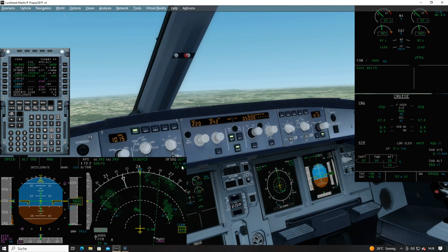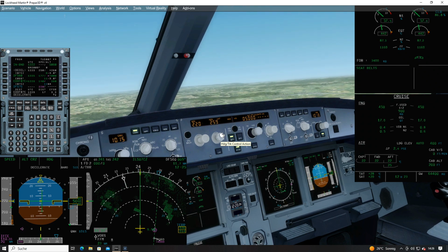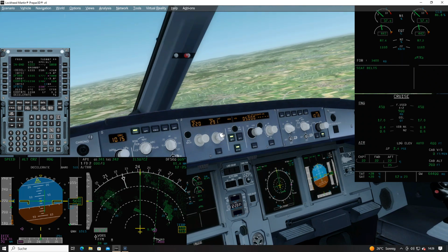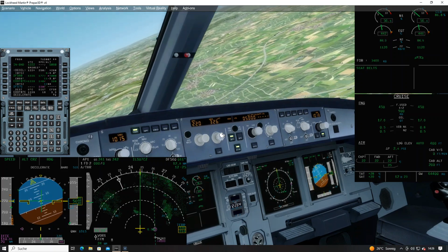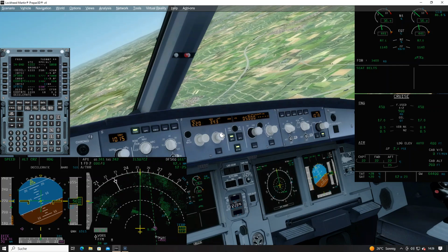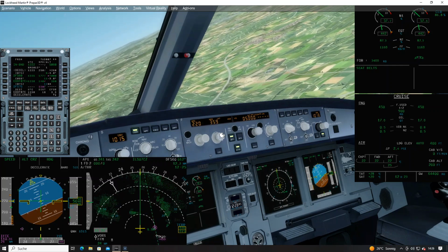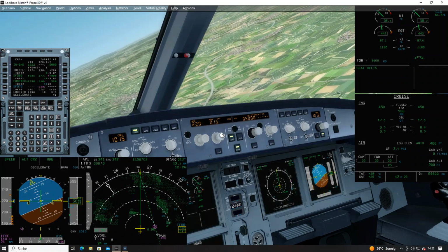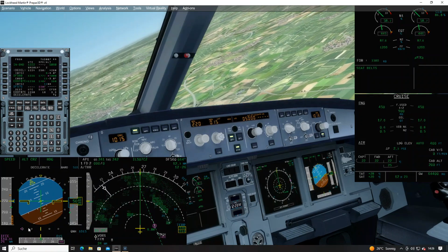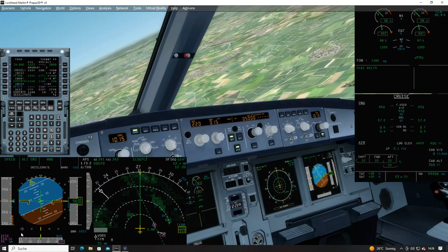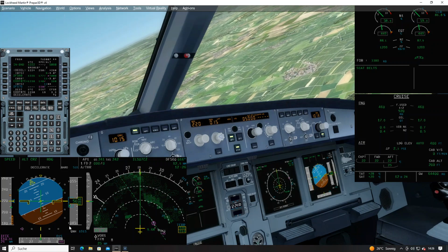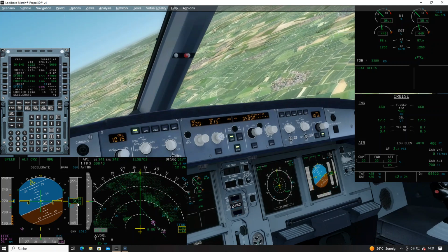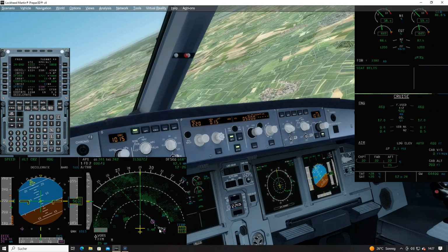Distance towards the point is 11 miles, which is quite okay, so we turn now to the right. Typical intercepts are on a heading of about 040, so 30 degrees off from the center line direction. I get a localizer indication on the PFD down here, which is good. But everything is looking good. Not everything. We're still at 5,000 feet. The approach is starting here out of 4,000.